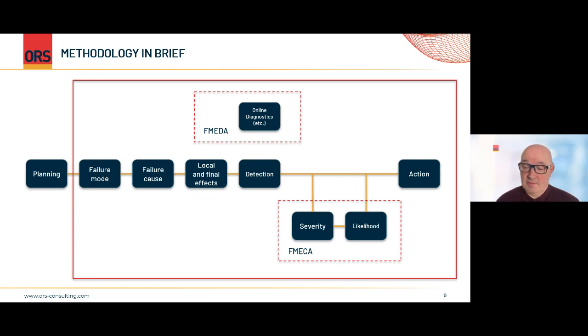So what is the severity in terms of consequences? Those could be safety related, they could be commercial, they could be environmental, or they could be more qualitatively defined, just in terms of, you know, catastrophic down to minor. The likelihood, on the other hand, that's obviously about the frequency, and trying to get some sense of, is this a 1 in 10,000 event? Is it a 1 in 100,000 event? Is it a 1 in 10 event? We're trying to get a sense of how often that happens.